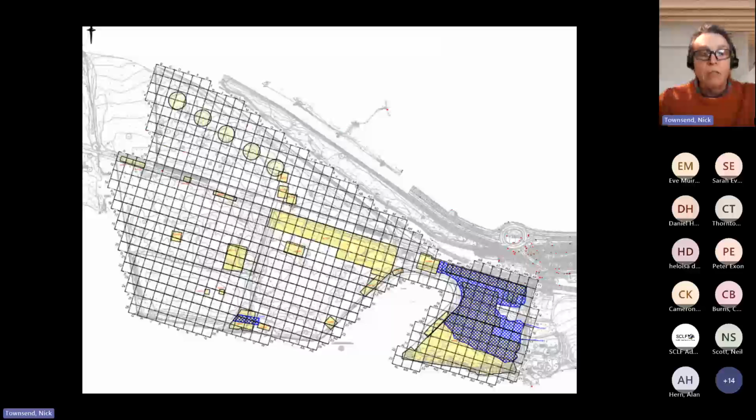So this illustrates the extent of the identified areas. As I said, excavations were to be extended to define depths, and validated to demonstrate compliance with site criteria. The excavated materials were taken to the platform, stockpiled in 100-cubic-metre piles and tested again to determine suitability for reuse, requirement for treatment, or off-site disposal.